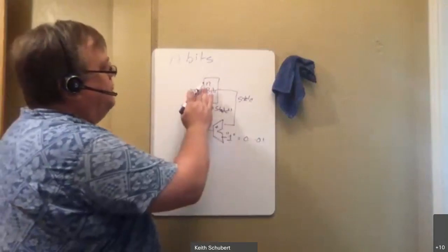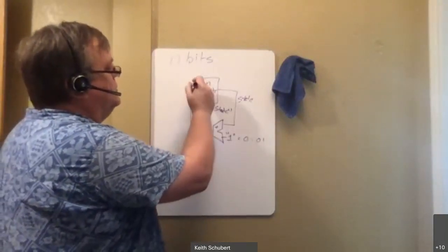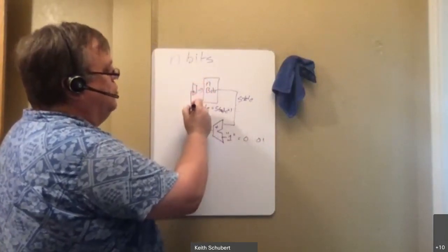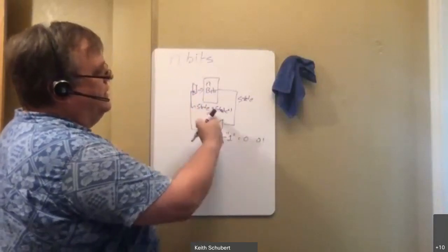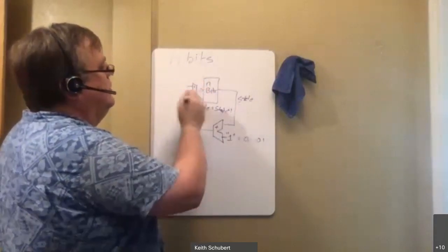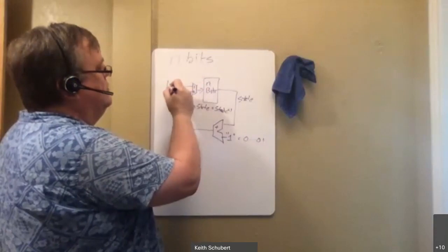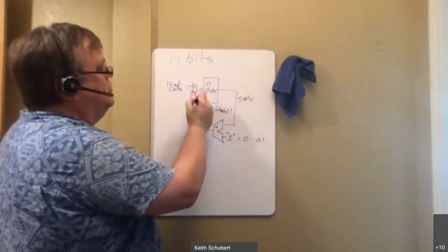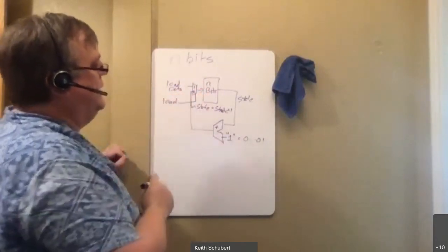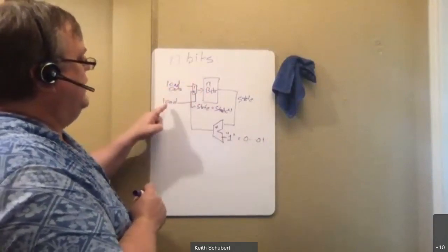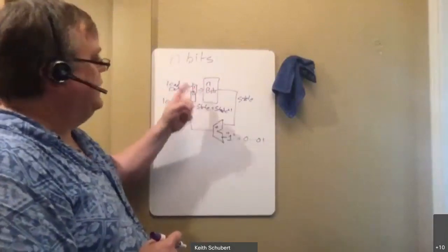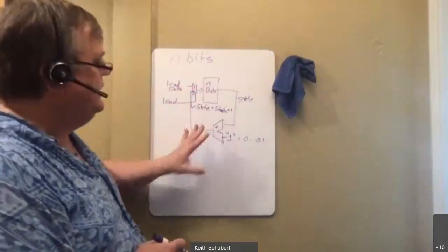Now let's say I wanted to have a parallel load. This is where I could put that mux in. I could say 0 is my normal run state. So I just take my next state, which is state plus 1, and I put it in 0. And then in 1, I can have my load data. And then the choice of this mux comes out. This is the load command. If it's a 1, it'll pull from load data. If it's a 0, it'll do regular addition. This is a very easy way to build that load command and functionality into that state.